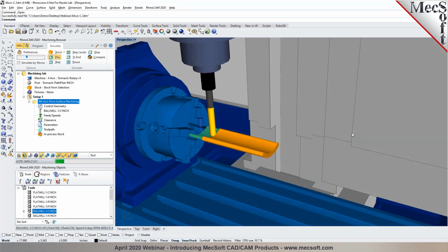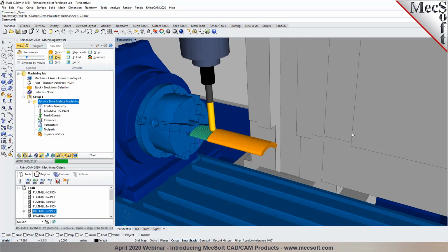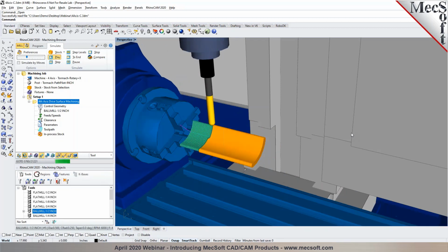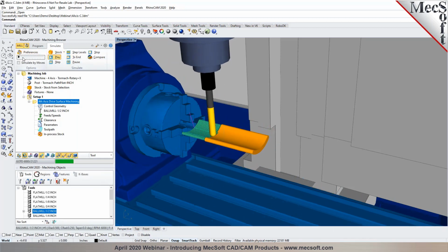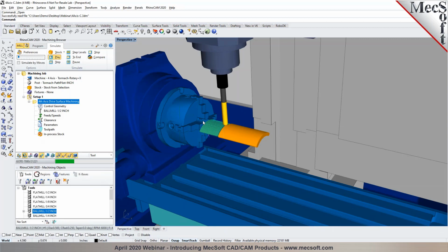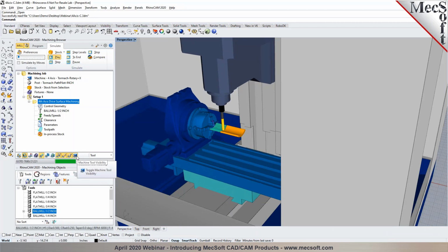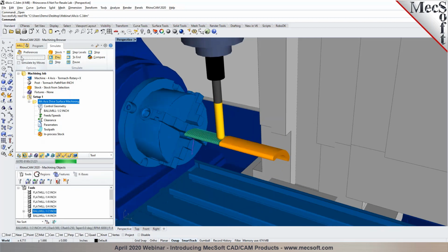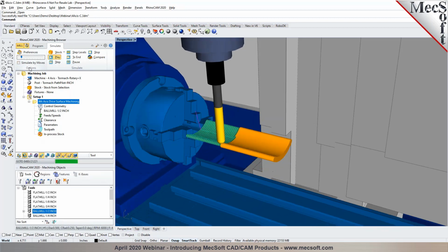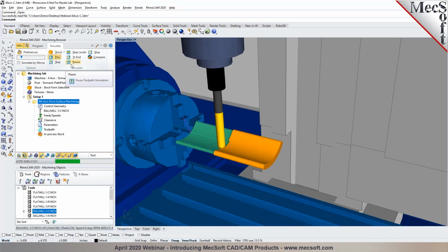So the multi-axis, the 4th-axis toolpaths, are available starting with our Expert configuration of our mill module. Expert, Pro, and Premium will include 4-axis toolpath methods. And this is the simulation with the machine tool. You can toggle the machine tool visibility by selecting this toggle button in the simulate window. So I'm going to pause the simulation here.